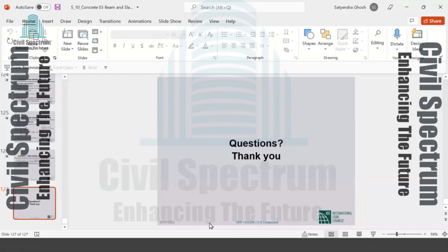There may be a tie between the ends, which will be the tension member. I don't think there is any shear involved if it is a real arch. Like in a truss, there is no shear. Shear is caused by bending. Right, arch is compression.